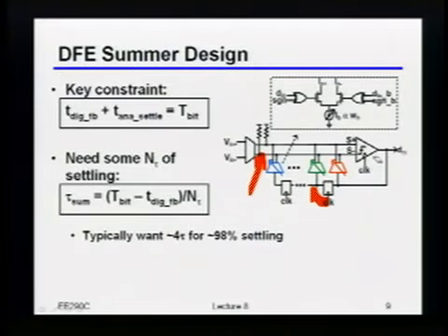Yeah, I'm making a bit decision, right? Exactly. So do I care if it's nonlinear at that point? I'll be a little bit careful. I only care in the sense that it'll change my amplitude, right? So it'll make my amplitude a little bit smaller, but as long as my voltage margin with that degraded amplitude is good, I don't care.